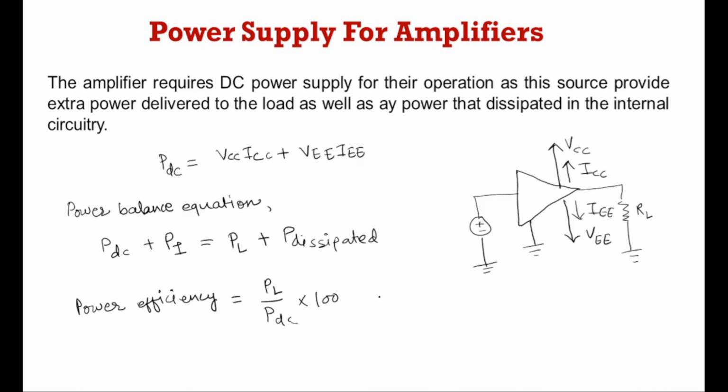One more thing, we know that the output signal of an amplifier has a larger magnitude than the input, but there is a limit: the output signal cannot exceed the level of the power supply. So there is a range for the input signal v_s so that the output will not get clipped off.